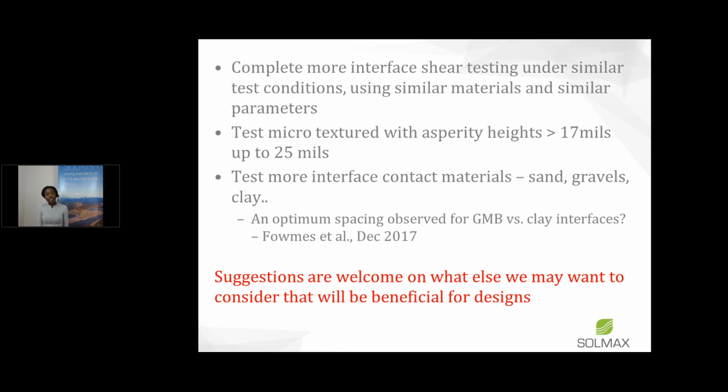We're going to test more contact materials. We'll test sand, we'll test gravels, we'll test clay. And also we want to look further into that position from that paper that was just published on optimal spacing with geomembranes versus clay interfaces with the asperity concentration. We'll look into that further. And we're also open to suggestions on what else you may want us to look at that might be beneficial for design. I received an email as well in relation to this webinar from another renowned person in the industry who I think has been looking at how to characterize asperity concentration.